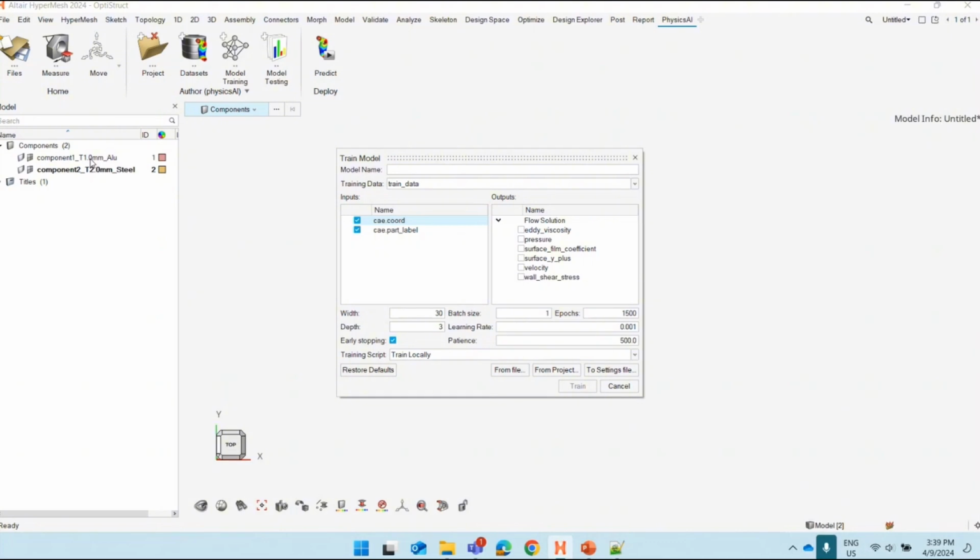that has this thickness. So this one we will not be able to reflect it, but at least you will know that this model A is causing these results. So you can rename your component. That will depend on your component name, rather than the varying thickness. So you will need to change the component name in order for it to recognize as a different component. Okay.